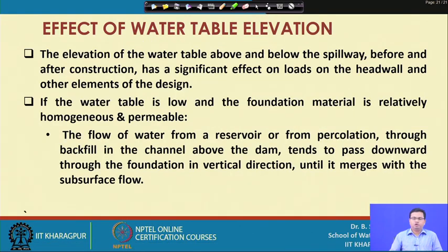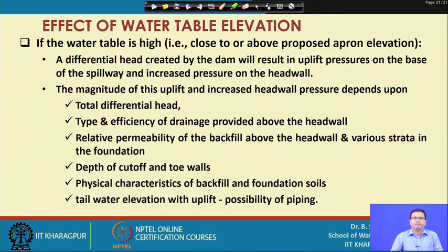Now, coming to the effect of water table elevation. The elevation of the water table above and below the spillway before and after construction has a significant effect on loads on the head wall and other elements of the design. If the water table is low and the foundation material is relatively homogeneous and permeable, the flow of water from a reservoir or from percolation through backfill in the channel above the dam tends to pass through the foundation in a vertical direction until it merges with the subsurface flow.